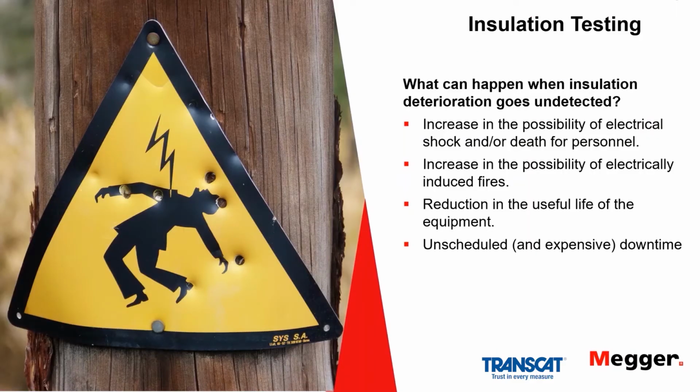And what are you trying to avoid then with insulation deterioration? Well, the first thing is, of course, human safety. If insulation breaks down and shorts out, the human can become the path to ground and be injured or electrocuted. So we want to eliminate that possibility from your living or working environments.